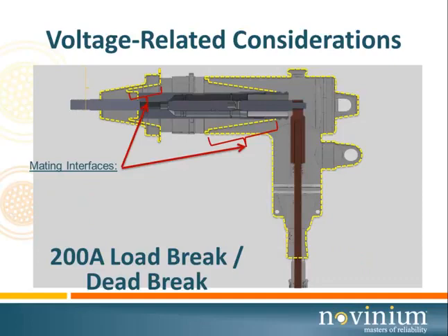Now, the more critical area for greasing is in these two interfaces. And by far the worst area is this, the operating interface. But for the minute, let's just look at the two of these together. We want to make sure that we use the proper grease. Now, the materials that are used to make almost all these separable connectors is EPDM. It's an oil-based rubber. If we happen to use, say, Vaseline to lubricate this surface, there is no doubt that it would lubricate it. You'd be able to put the elbow together and it would work fine.